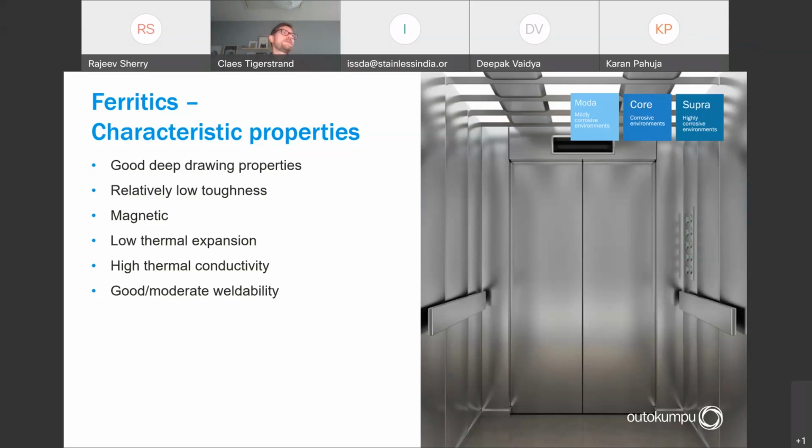With the ferritic structure also comes a lower thermal expansion than you have on austenitic grades. That can be very useful for high temperature use when you have, let's say, high fluctuation in temperature, so you can keep the thermal expansion at a lower level to avoid thermal fatigue, for instance, that can crack the material.